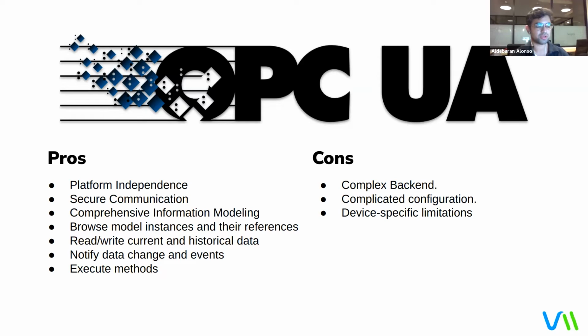For example, in this protocol, you can use a more object-oriented way to model your device, so that you can expose the temperature and how the data is encoded. It can also have a status related to the device, so you can share with the machine whether the data is reliable or not, and we will show how this is done in the demo. But this is way easier than Modbus, and more reliable and better described than in the Modbus way.